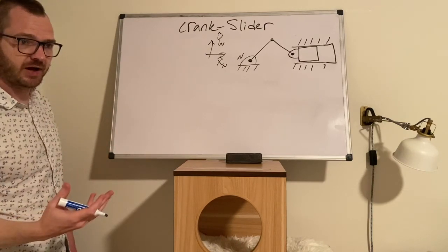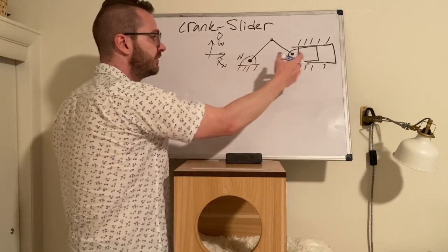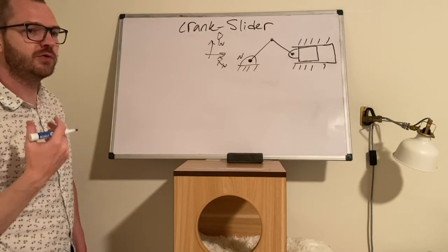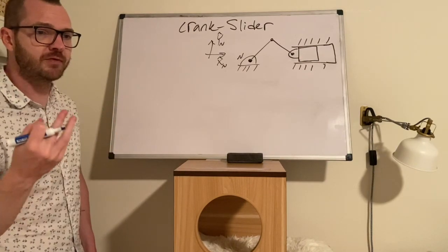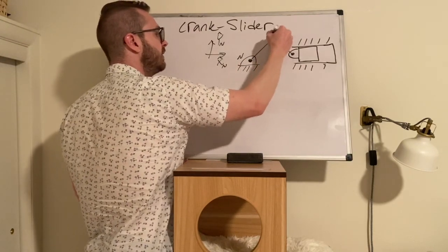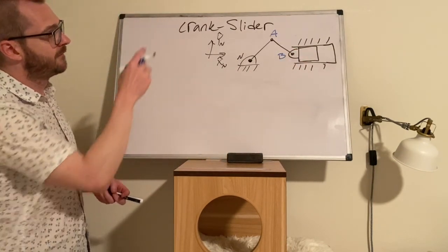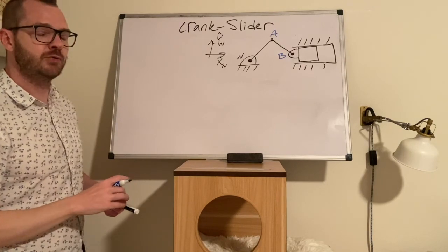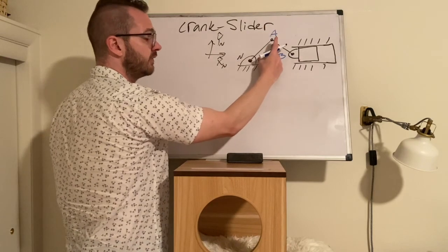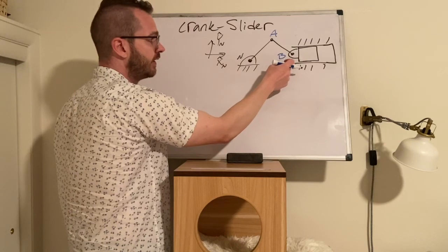As we've talked about several times, positions, right? We need to be tracking some kind of position on every single body. This is a good example of maybe we don't have to do 3 more points, since there's 3 bodies. For example, if we put point A on this joint and point B at that joint, those 2 points actually do a pretty good job of tracking those 3 bodies. Point A is on body A, and point B is now the tip of body B.